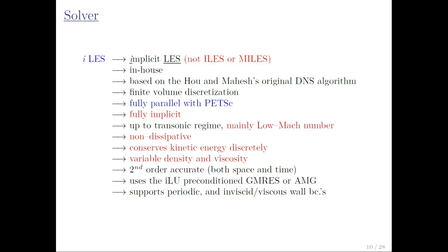Could you comment one more time on the difference between your implicit LES and the other? The term here represents its fully implicit nature coming from the discretization. The term implicit LES or monotone integrated LES comes from the dissipation.